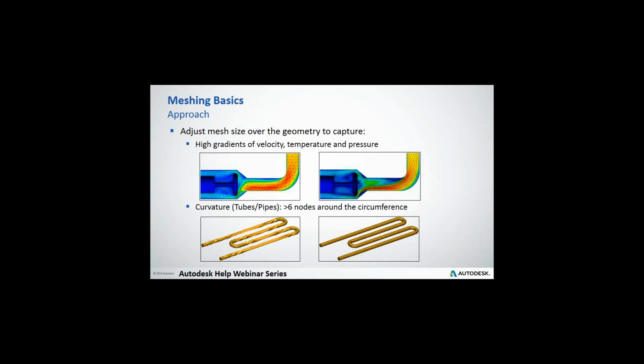At the end of the day, as far as the geometry, your mesh is your model, not your CAD model. Once you mesh it, your actual model is the mesh. It doesn't matter if it was a circle that was converted to a six-sided polygon. That's what you have. You might as well have modeled a six-sided polygon in your CAD model to begin with, if that's your mesh.